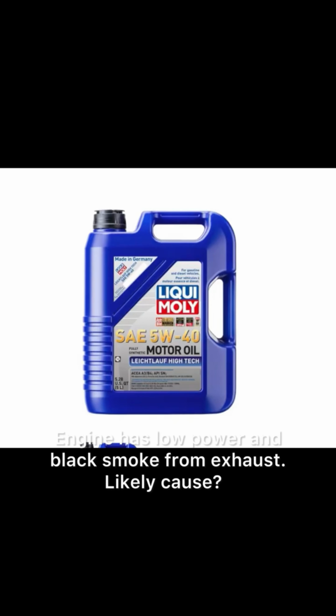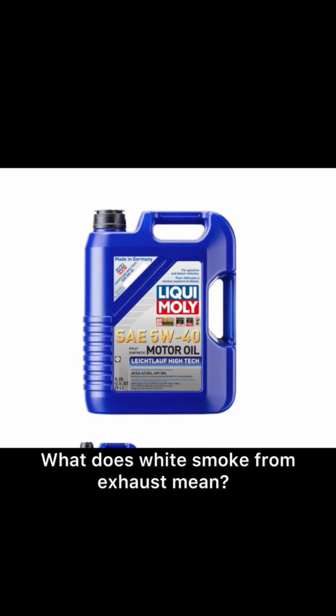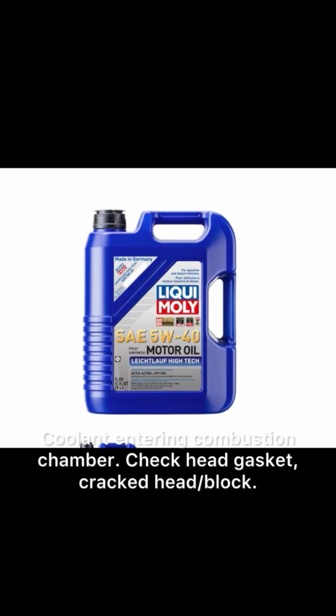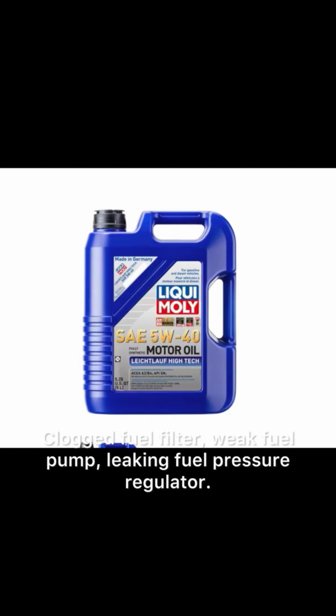Engine has low power and black smoke from exhaust. Likely cause, overfueling or restricted air intake. Check air filter, MAF sensor, injectors. What does white smoke from exhaust mean? Coolant entering combustion chamber. Check head gasket, cracked head/block. Fuel pressure is low. What are 3 possible causes? Clogged fuel filter, weak fuel pump, leaking fuel pressure regulator.